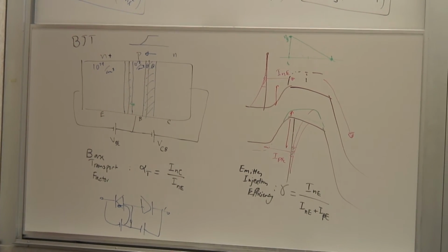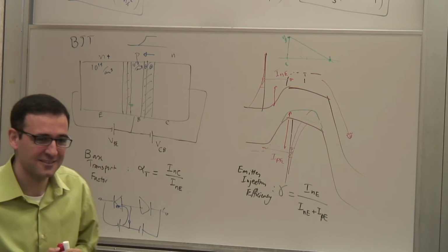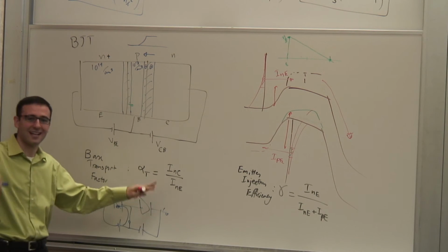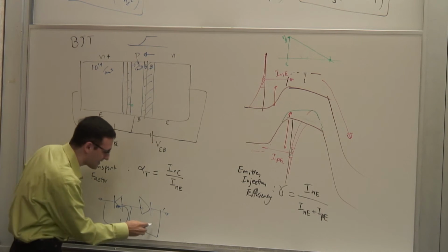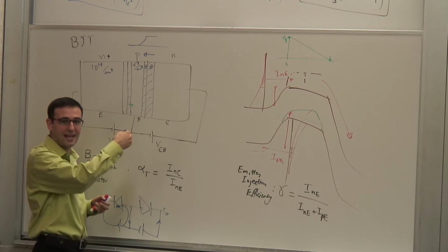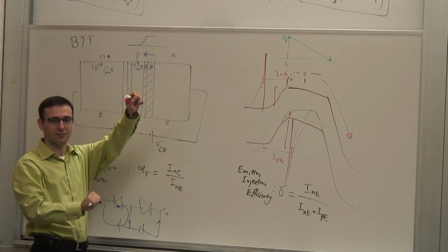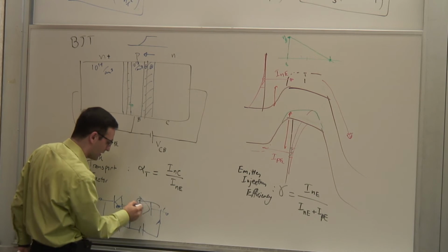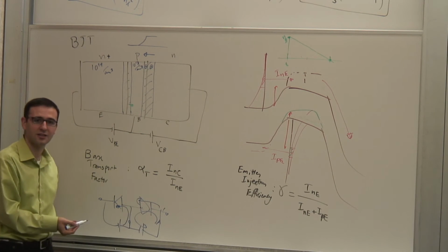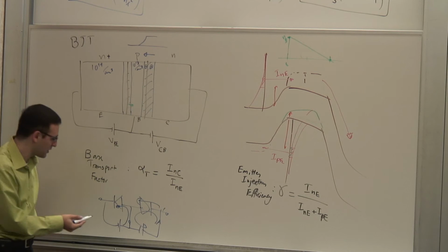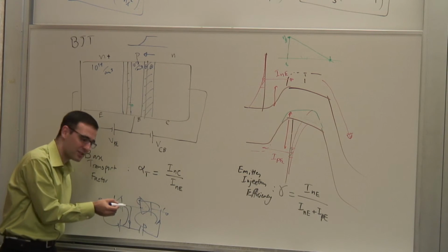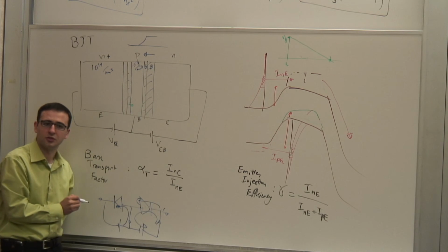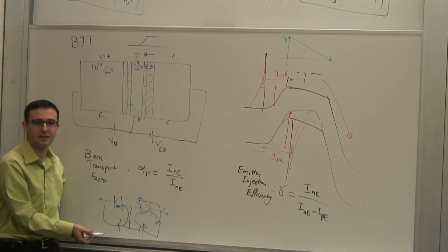What if you use a Zener diode and then you exceed the Zener potential? Okay, well, no, again, that's a secondary effect. But even if you do that, you'll have a second current. So you're saying that if you break it down, right? No junction will last forever. If you apply a very large reverse potential, it will break. And so you will have a second current flowing through here that's independent of that current. The key for transistor operation was making sure that this current is controlled by this voltage. They're not completely independent of each other.